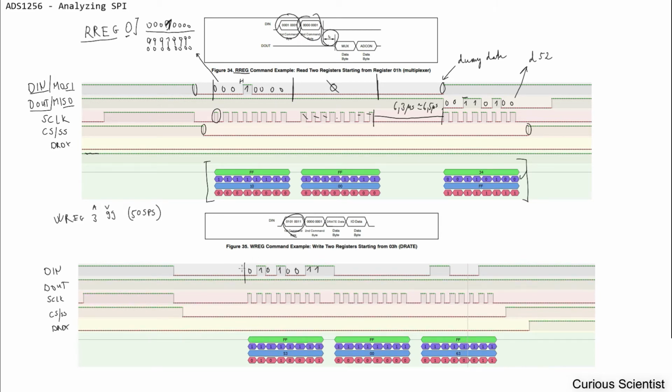And now I can show you a better example than here for the combination of the two things. So we have these write register and 3 combined together. And how? So let me show you. So we have the original number 0101 0011, and then this is basically the combination by the OR operator from the following. So the write register command individually is 0101, and then the last 4 bits can be all zeros.